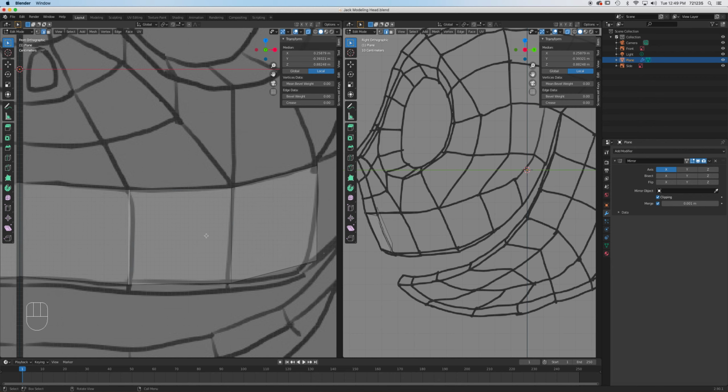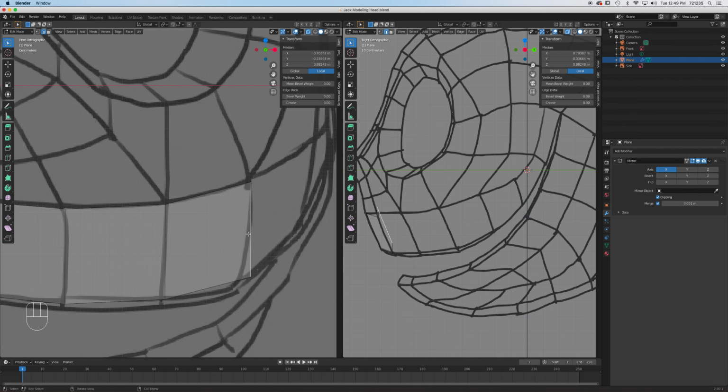And one way to check, I mean, you can merge vertices by distance later on, or what we used to call remove doubles. But if you're not sure if you got one, simply select that and press G. If nothing is coming out, then you don't have anything extra. This is what I mean by that. So let's say here I press E, I extrude, and I right click, and then I got distracted, and I forgot I already have an extrusion, and then I went in there and started extruding again. So there should be another one right there.